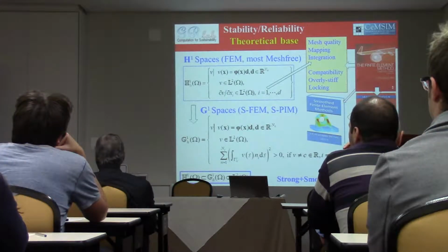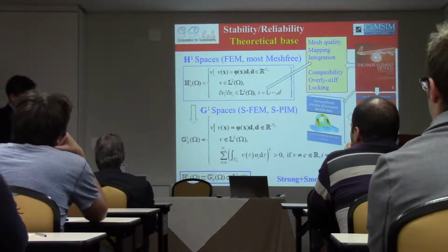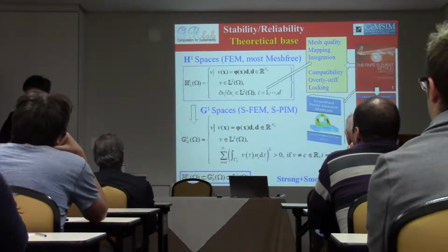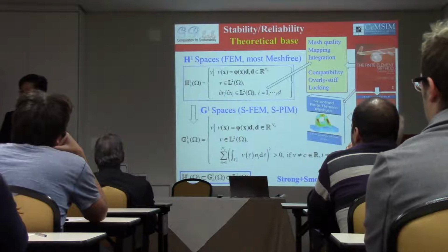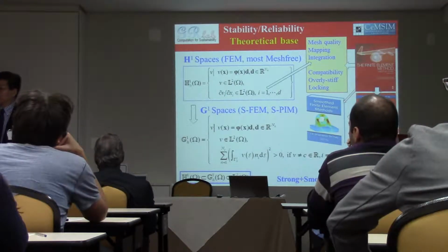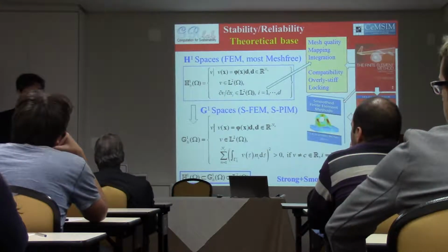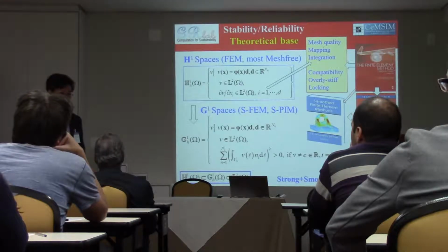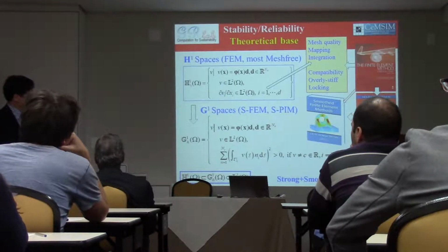This works well for the finite element method, but when you use FEM, you may notice that if you choose a class of elements we call the triangular element for 2D or tetrahedral elements for 3D, you find the solution is not always so satisfactory, especially when you look at the stresses in the structure. There are reasons for that.